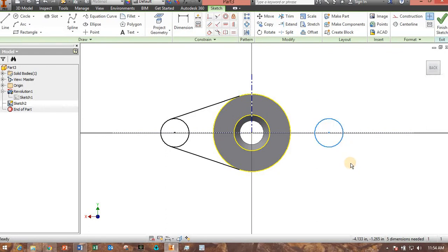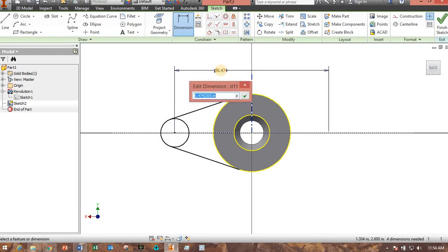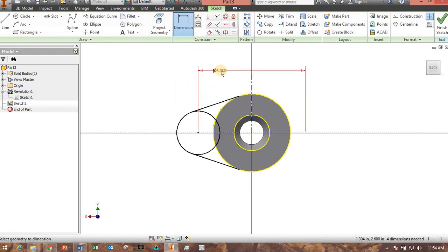And we could even delete that and we'll mirror. So let's delete that one because we're just going to mirror this to the other side. Okay, let's add in some dimensions here. Notice this dimension is given as a radius, and this is a diameter here, so let's do 2 times 0.75. There it is.